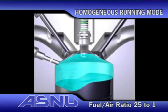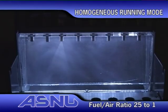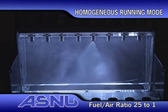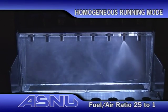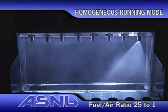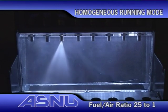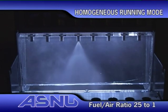Homogeneous running mode. This mode is what would be called a normal combustion cycle, with an air-to-fuel ratio of 25:1. In this mode, the injector delivers a normal amount of fuel into the combustion chamber. This gives the engine the required performance as the car goes faster. The engine management system determines when the system needs to switch between the stratified charge mode and the homogeneous running mode.